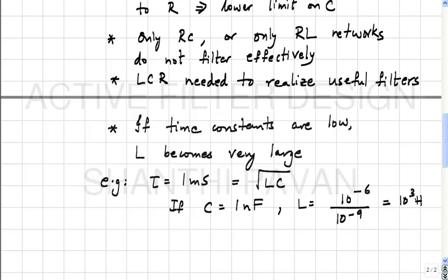And then they realized that, hey, if you want to build a 3 kilohertz filter, you need oodles of inductance and capacitance in order to get poles at such low frequencies. Okay. Now, 3 kilohertz is therefore a very reasonable frequency to work with. All that I am pointing out is that 1 millisecond is not an impractical time constant to realize. Of course, now we also have applications which go down to several millihertz.